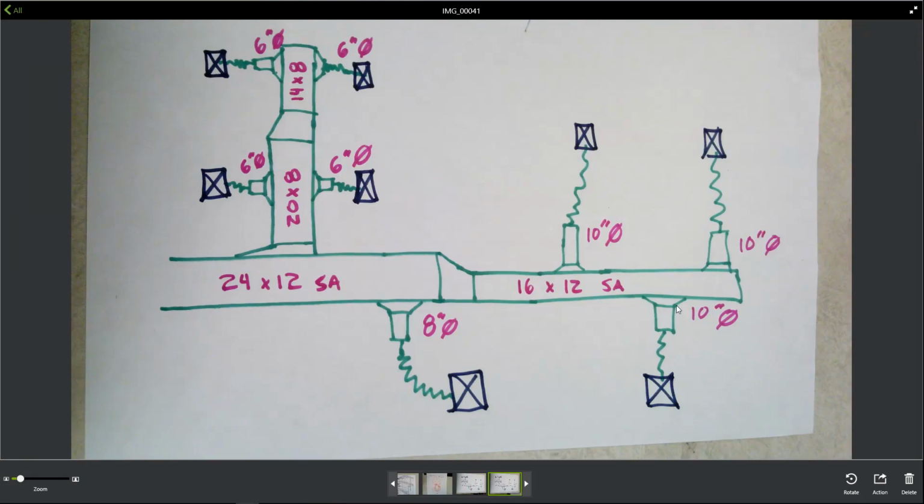Alright, so at this point I'm going to come back in and I'm going to draw these. This is a little bit different than this one, where this only has the takeoff in one direction here. So basically this is to show that we have airflow coming down here and being directed into this branch line, whereas this is a round takeoff for connection for flex duct. So this represents a conical object, ductwork in plan view.